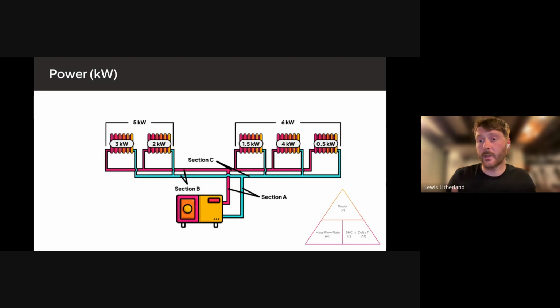Like, we can work out what it could actually be. And this is where, once you see this on a screen, it's like, I know it's so very basic, but it's like, oh yeah, actually them rules of thumb don't make any sense, do they? Because what's this rule of thumb of no more than 3 rads or 15 mil? It's like, yeah, but what was the kilowatt you're sending down? You could have been sending 0.1 kilowatt down to each rad, or you could be sending 3 kilowatts down to each rad.